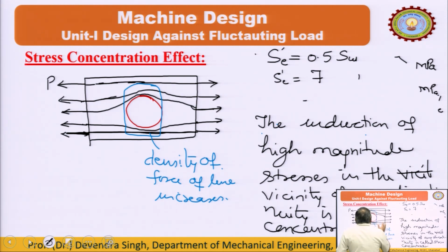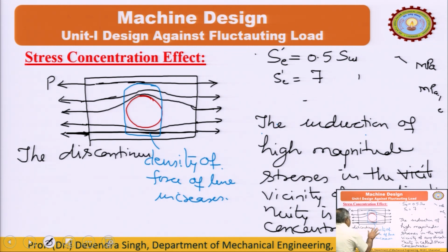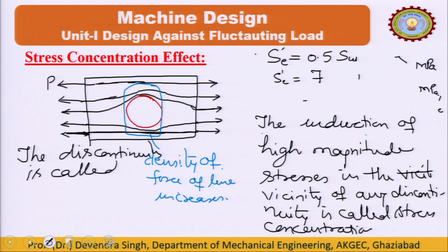And the discontinuity is called a stress raiser. This may be a hole, this may be an abrupt change in the cross section area like a stepped shaft.